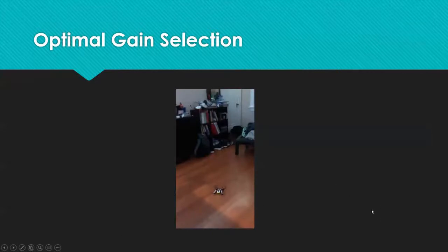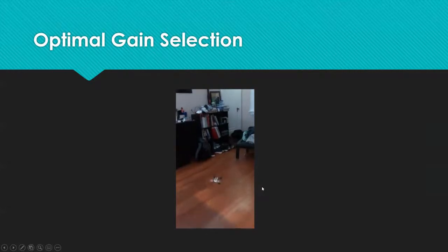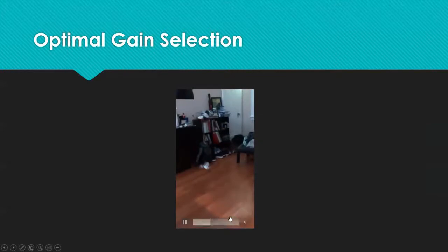And so once the controllers were implemented, it became just a matter of tuning the gains, the filters, and the state estimators. This was a process that we did not entirely complete, although we did make significant progress towards maintaining the hover. One thing that became clear very quickly was that the UAV was susceptible to drift. And upon looking at the optical flow data, it was clear that the sensor was the underlying issue. So you can see here that's the drift that the UAV was experiencing.